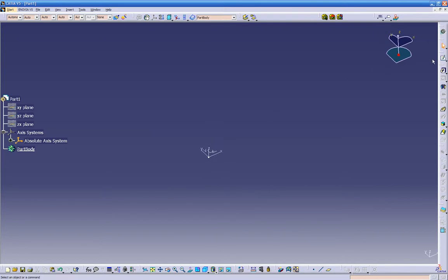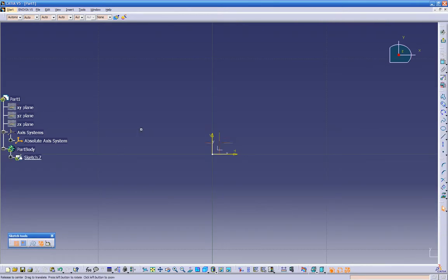Let's open a new sketch again. Let's go to plane. It's gonna ask you down here, select a plane or a planar face or a sketch. We can click on one of those planes. We can click on XY over here, XY plane. We can see it on the top right here. So if we click on the Z, it's putting our part on XY plane. Or we can click on XY plane up here, which is the same thing. Now we're back on the sketch.